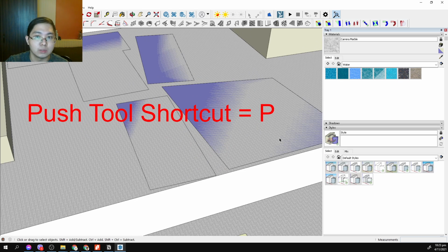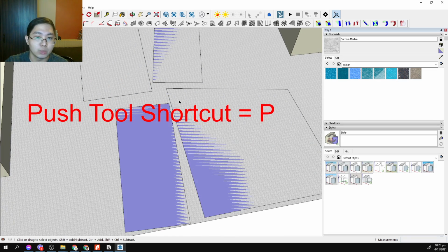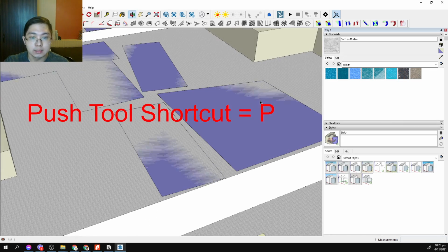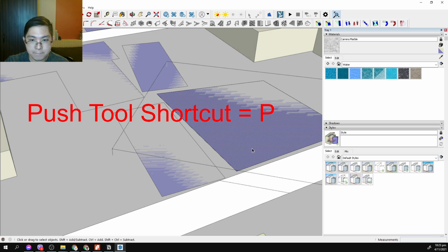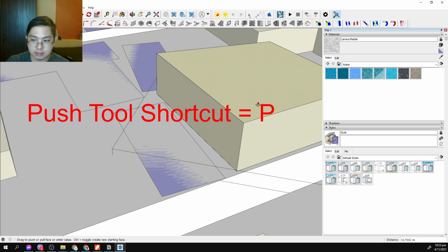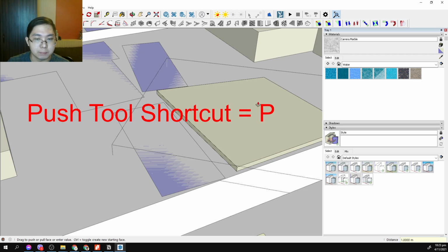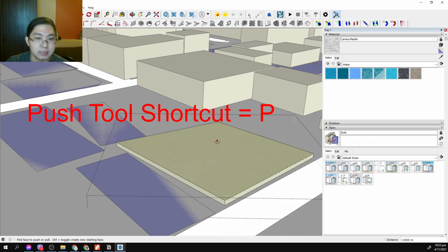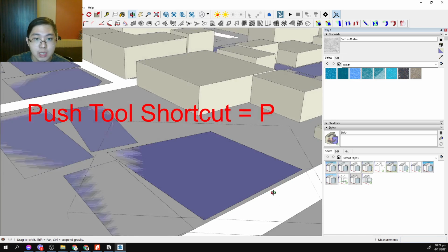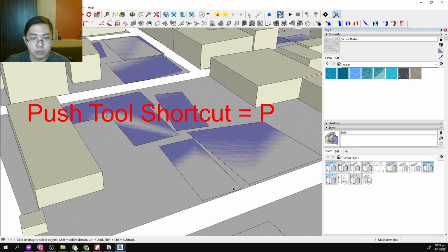It's better that we do not raise it so that it will maintain this blue color so that I can manually do it myself. Because if you raise it and let's say you don't know and you just put 1 meter, it will turn the same color as the raised buildings, and it will be very difficult for me to find and difficult for us to remedy.